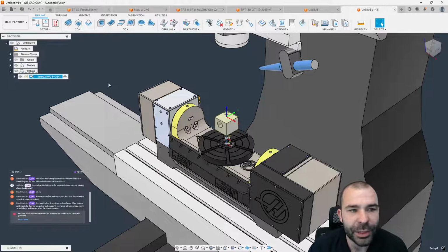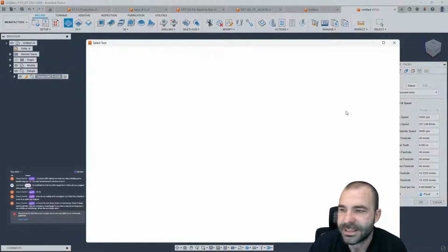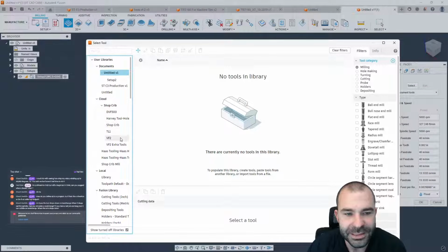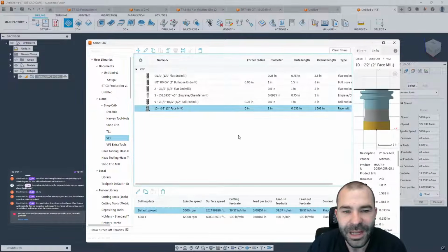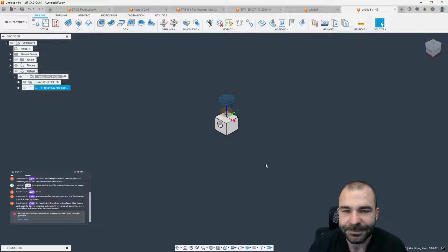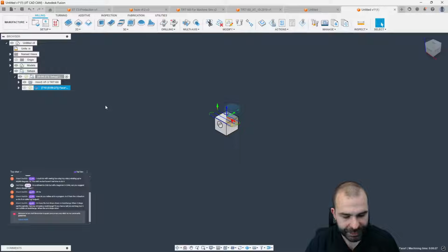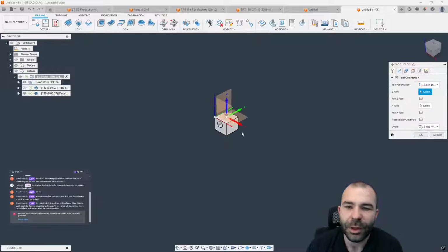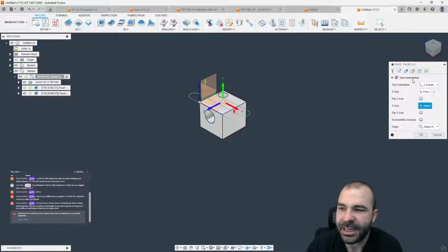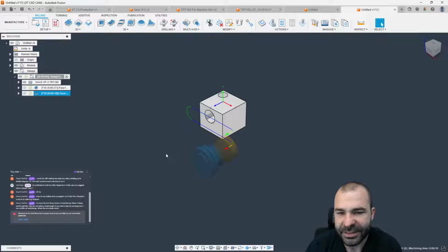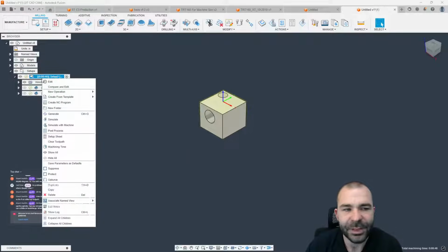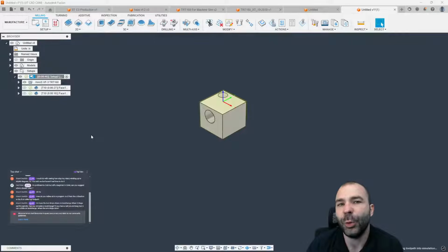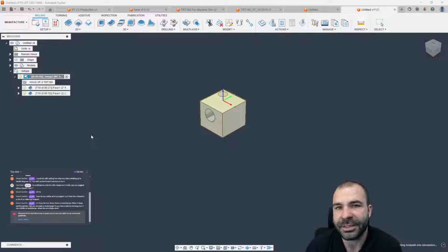We're going to go in and create a couple of toolpaths. I'm going to face this guy off with the good old trusty 1/2" end mill. No, we're going to go 2" face mill here. And then I'm going to duplicate that using Control D as in Delta. Just allows me to create another version of that. Again, we do our tool orientation down to this side now. Again, facing off the side of our part. And this will give us something very simple to go in and actually simulate with machine and do all our checks and balances of whether or not this is going to work.